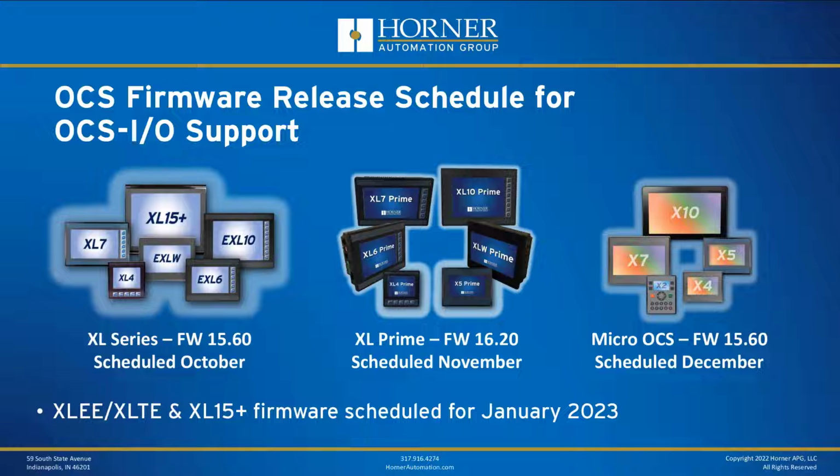The bottom connector, the 6-pin connector for power, is definitely correct. So I'll get that taken a look at. I'm sure that was probably just a section that may have been copied from SmartRail, since that was how SmartRail is recommended to wire. But for these modules, it is absolutely recommended to use the onboard 6-pin connectors for power.